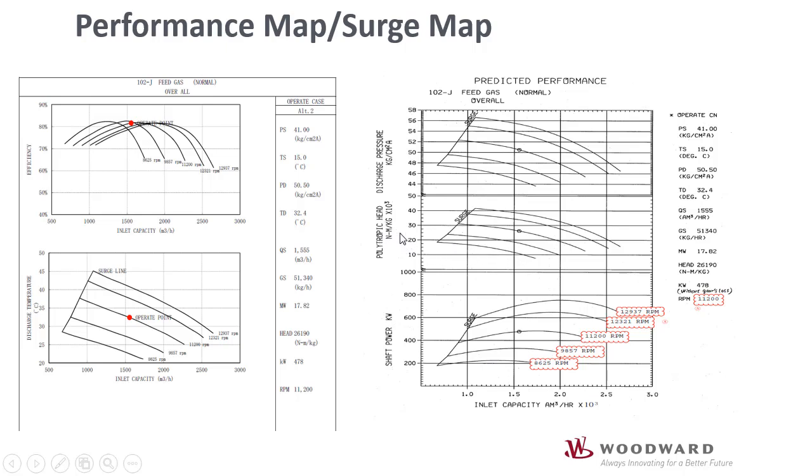However, some users need discharge pressure versus flow. We can use polytropic head versus flow configuration, and later we can change the map display type to discharge pressure. Another map display type is pressure ratio versus flow, which is not mentioned here, but that is also common.